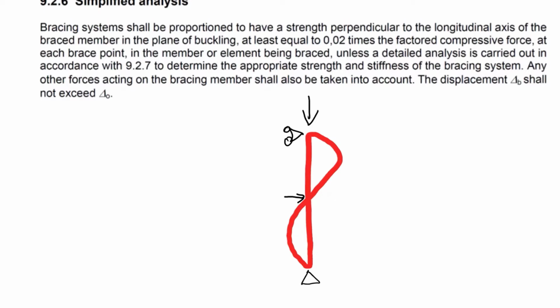And then we had floors that were bracing this column. And I forgot to specifically check, could the floor members carry this sideways buckling force? And then suddenly when the column was going up, I thought, oh, hold on, let me just go check that, because this is a very small force, but a small amount of a very big load is still, maybe it can buckle my floor. Thankfully, it was all fine. It wasn't an issue. But you will need to check this once in a while.